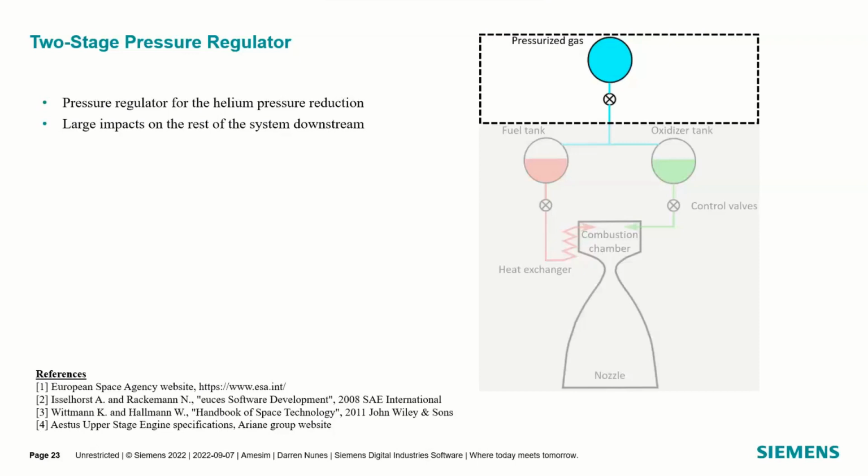We wanted to be able to control, mitigate, and compose such a stage system to match that, right? The pressure inside of the helium tank evolves from 400 bar A to 60 bar A, so a single stage pressure regulator could not have the actual progressive behavior. We had to do it over a two-stage process.